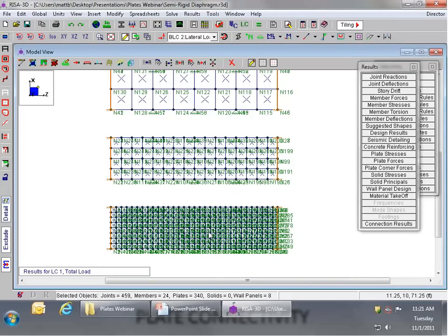If you've done a 2x2 submesh, thereby making your model 4 times larger, and your results have changed by only 2%, you really don't need to take it any farther at that point, because you don't want to slow things down and bog down your solution. And more importantly, you don't want to have a large amount of results to have to sift through later on. And we're going to see that when we get into results interpretation.